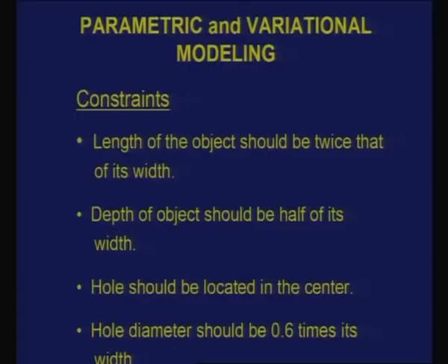Now, take care of those 6 parameters which are used to define the object together with the designer's intention. The number of parameters effectively reduces to a smaller number. You do not have to provide all the 6 values in order to define the object, because these constraints will reduce the number of inputs which need to be supplied. When the designer comes up with these constraints, it is usually based on certain functional aspects. Many times the constraints could be conflicting too.